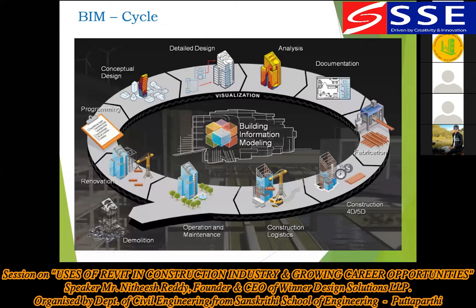BIM is something like not even an ocean, more than that. Renovation will be all done using the reverse engineering concept, and that will be mentioned as ReCap. ReCap will be used for scanning the data of the complete building. You need not go to the site. If you have a ReCap Faro scanner, that will capture all the data of the building, and from that you can start modeling and renovating the project.